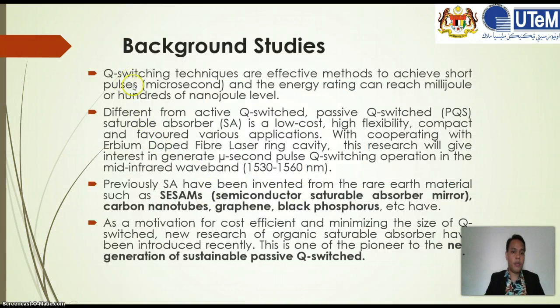The background of this research is that Q switching techniques are effective methods to achieve short microsecond pulses, and the energy can reach millijoule or hundreds of nanojoule level. Different from active Q switch, passive Q switch is low cost, highly flexible and compact, and also favored in various applications. So with the erbium doped fiber laser as a gain medium, this research will generate microsecond pulse Q-switching operation in the mid-infrared waveband.